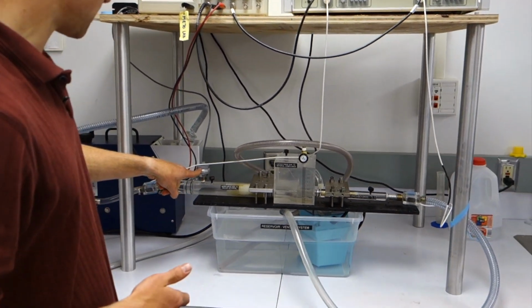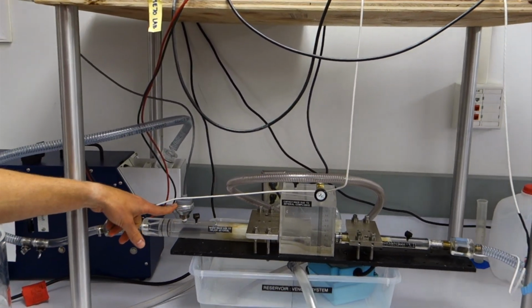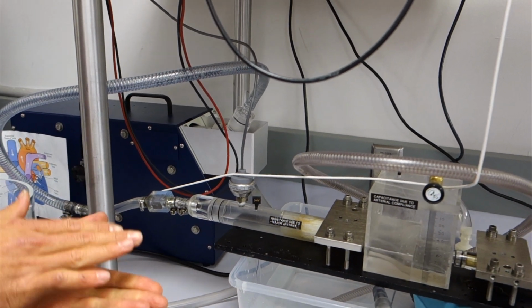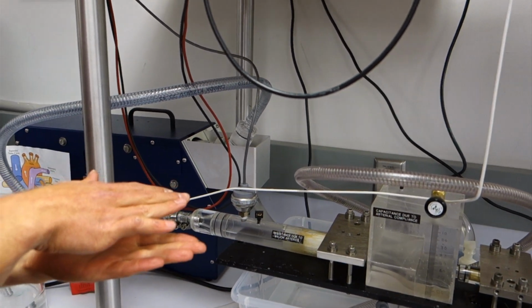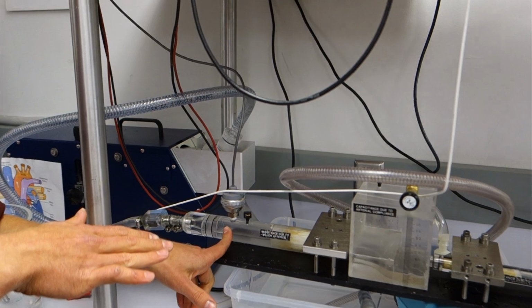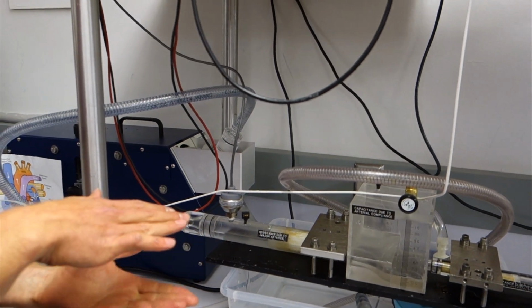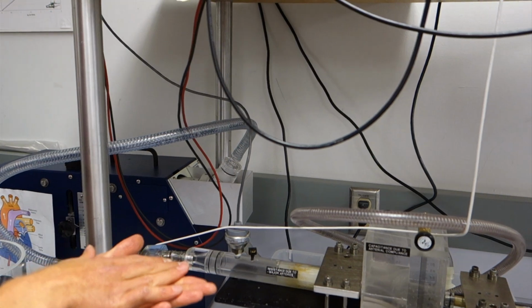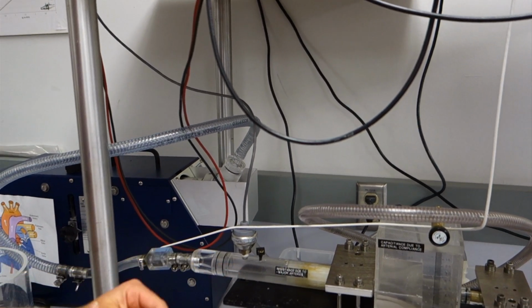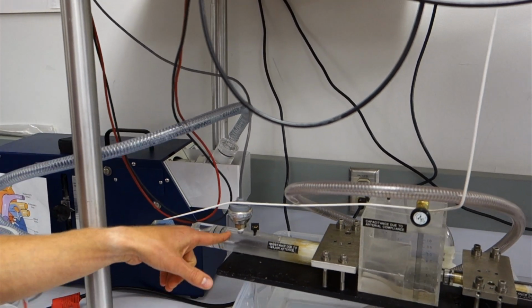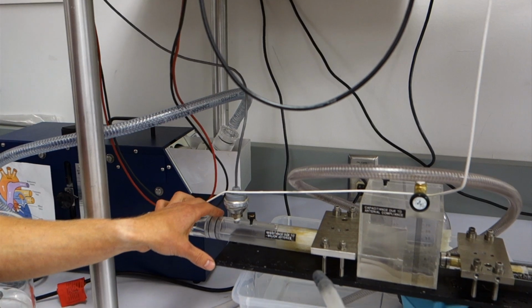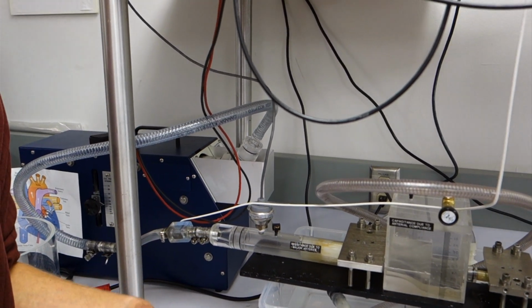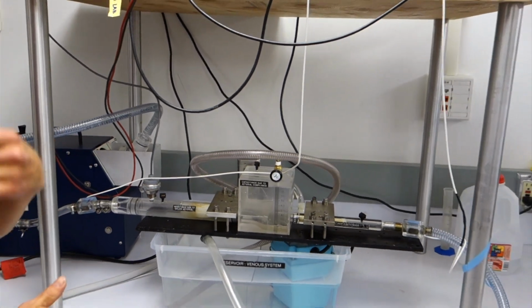This is the pressure transducer, and we could have intuited that based on the fact that it kind of looks like it could be a capacitive pressure transducer. So there's a membrane in there which gets deflected via the static pressure of the water, and that deflection changes the capacitance value of the capacitor, which is then picked up in a circuit to back out what the pressure is. And it has an output of 1 to 6 volts, which corresponds to pressure of 0 to 10 psi gauge pressure, which we're going to write on the board in a second.